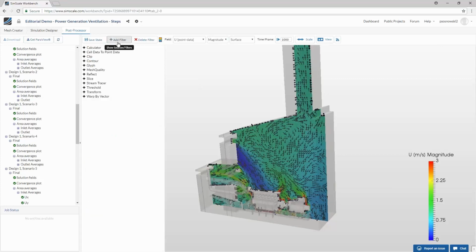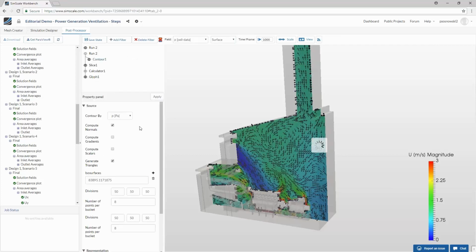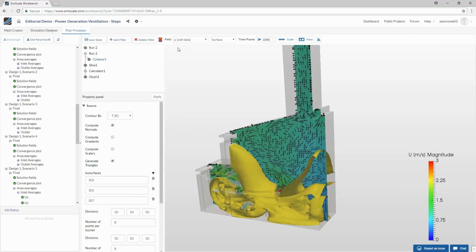And there are more interesting post-processing tools, like let's say that we would like to see where the temperature is very high. So I can choose contour, and contour with temperature. Please take your time while typing the questions, but I'm definitely here all the time. We'll be waiting. In the meantime, we'll set up a few contours of temperature, to see where we are at. There we are. So each of these surfaces will denote a different temperature level.